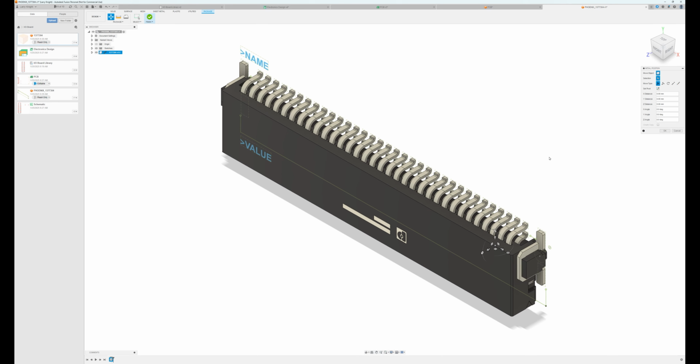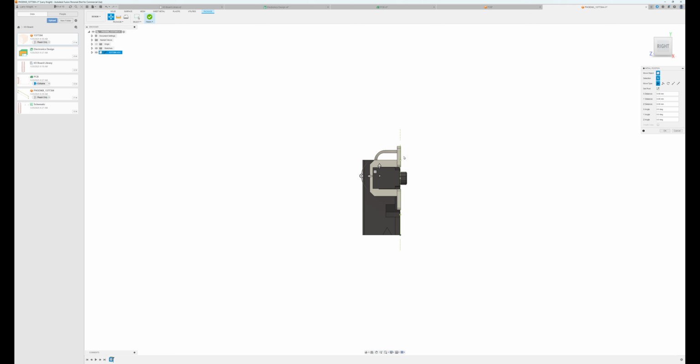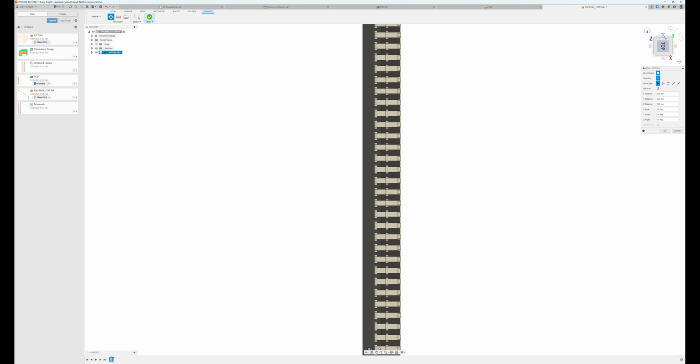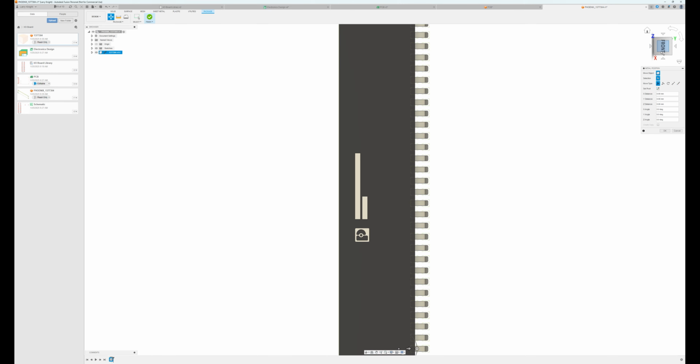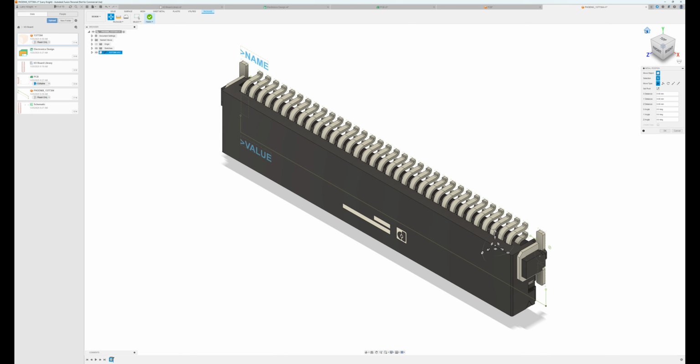If you're lucky, it will go right in on the footprint. You have to double check and make sure that it's lined up properly, because sometimes it won't be. Sometimes you'll have to manually align it yourself. But that's on the pad, so that's the way it would be on the board. So you go up here to finish, click finish, and save it. And okay.